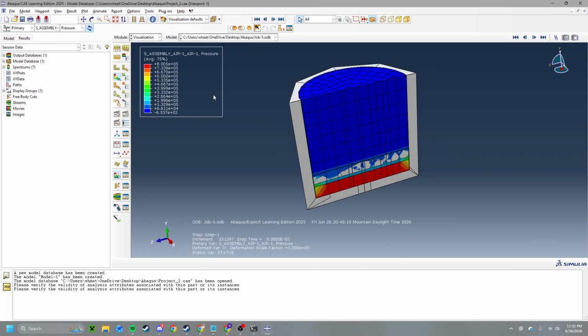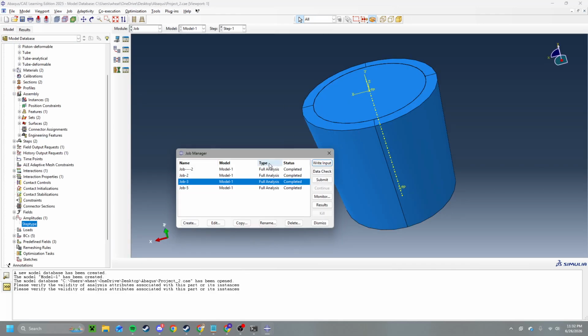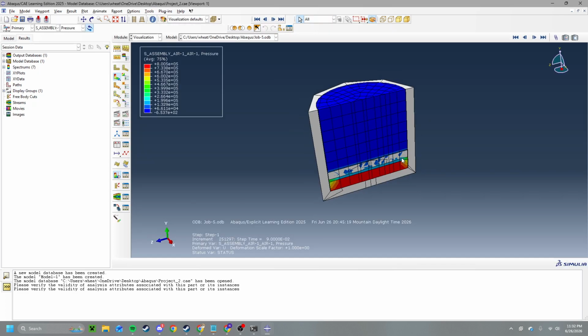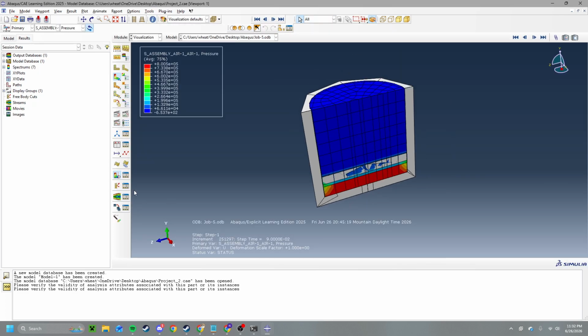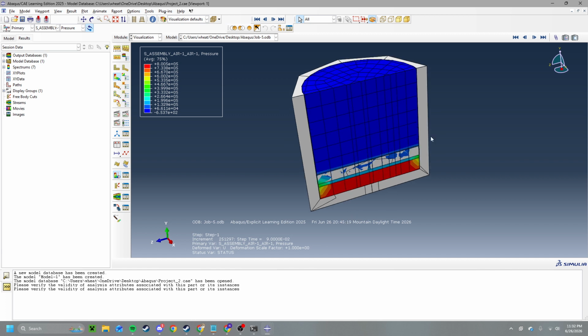And then I can show you, there's another kind of special thing in here in the visualization. You can see here, since you can't really exploit symmetry as well as you want for a Eulerian component, because of just generally how it works. The mass would be flowing out, and then it would flow in, and if you're blocking that mass, you're going to make some additional stresses in there and velocity barriers, and it doesn't work very well if you exploit symmetry.